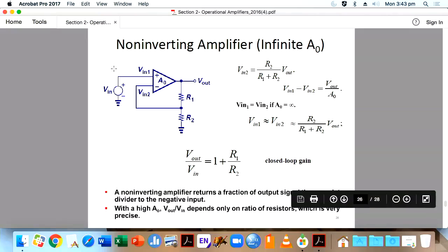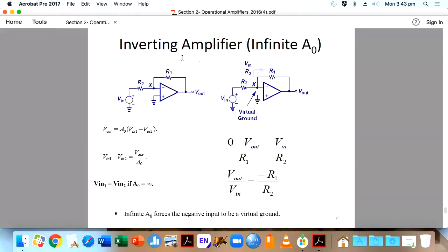Why? Because when you look at here, your signal is going into the operational amplifier and the input impedance of the operational amplifier is very high. But when it comes to inverting, you got a resistance R2. So that is not good. You don't have a very high impedance.